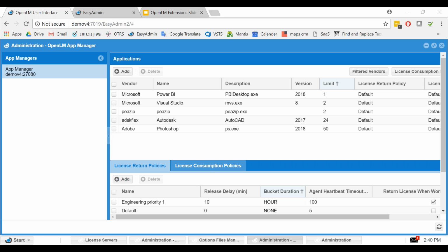So any app using FlexLM can be suspended. The work won't be lost. The app will just not be usable until you get the license back. This is what Michael is asking. So indeed, any app under FlexLM can be suspended, and it will not be usable until it gets the license back, because we suspend the process. You can't unfreeze the process.